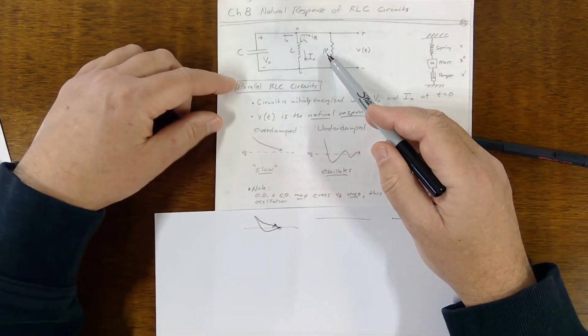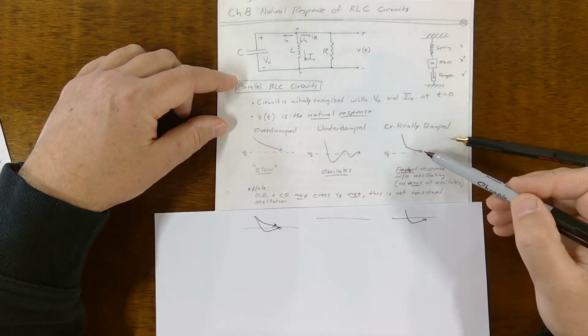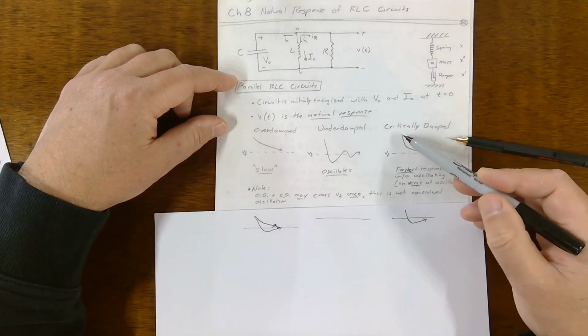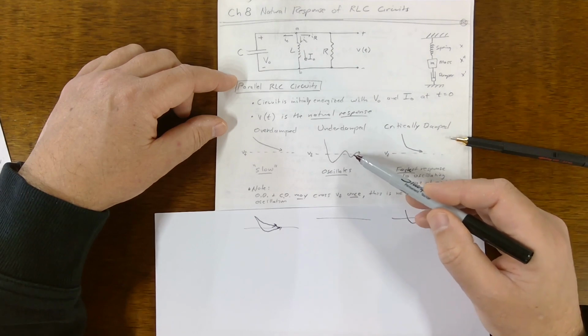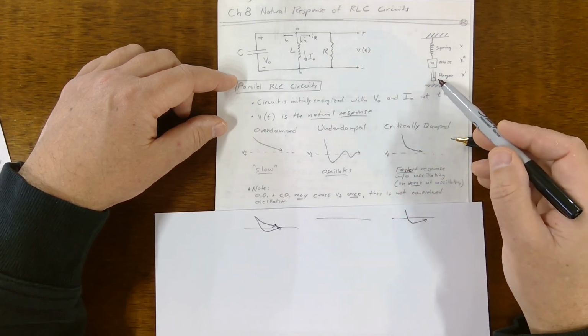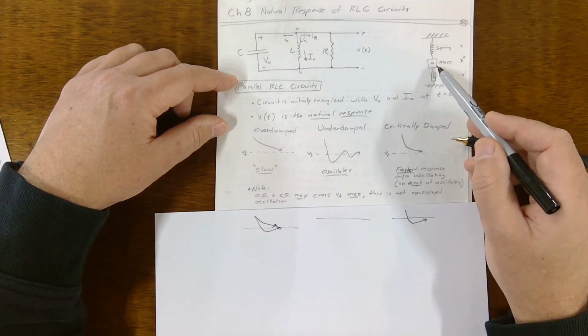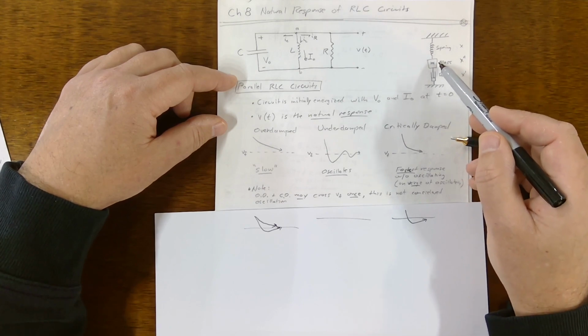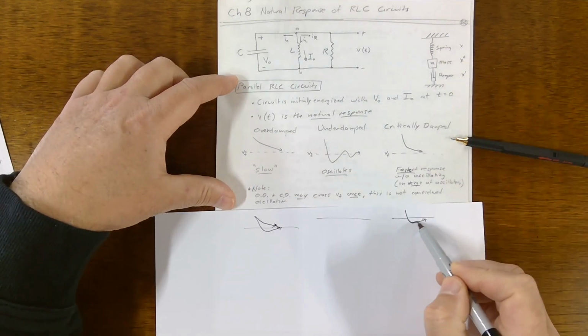There's a resistance value that's perfect, which is critically damped, which will cause this to go down to zero as quickly as possible without any bouncing, right? That's what you want your shock absorbers to be on your car. You want them to be critically damped, right? So you push on your car or this mass, you want it to come to its neutral state as quickly as possible, and it might pass zero once.